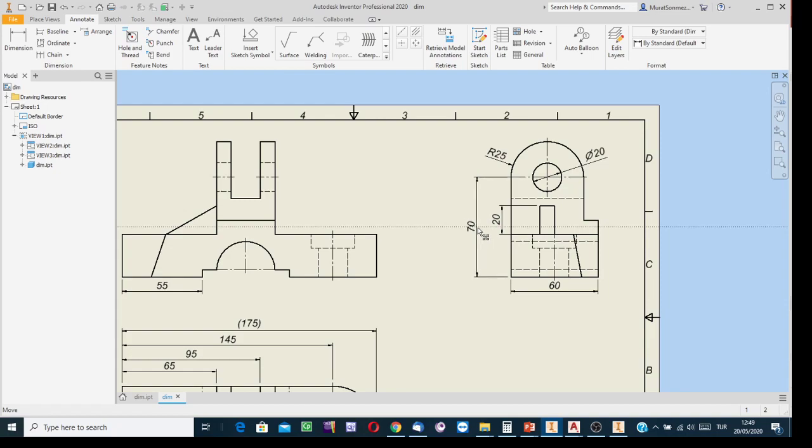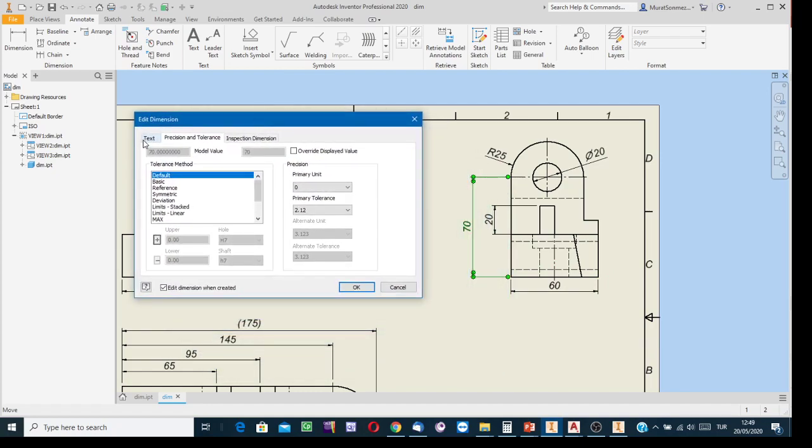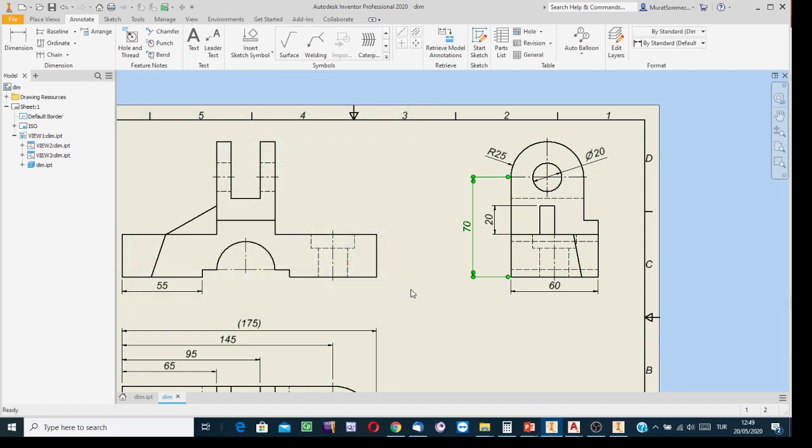Following this dotted line, you can make the space between this dimension line and the boundary larger, to be able to find the space for showing the dimension of a smaller feature. Yes, these are editing techniques. If you need to take the dimension into edit mode again, how? Double click on the dimension, then you find the same editing dialog box if necessary.